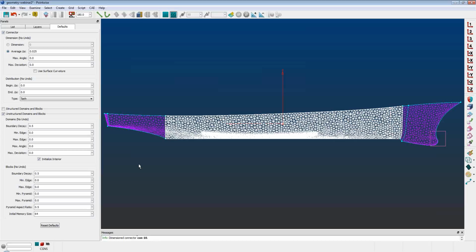Yeah, let me clarify that a little more, since I think you have a pretty specific use. The way Pointwise works is that it works on names. The surface meshes are looking for the names of the geometry surfaces. In this case, we have a hull surface mesh, and it's attached to, say, hull surface 2. Even if they came in a different order, if the new geometry has the same names, Pointwise is going to know to snap those meshes onto the geometry, even though it's modified. It's looking for the name.